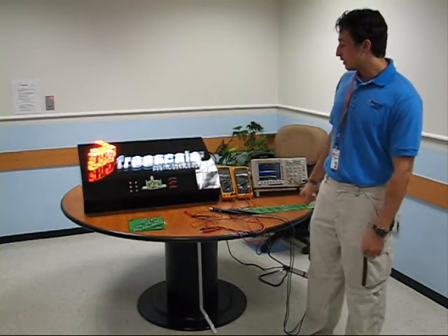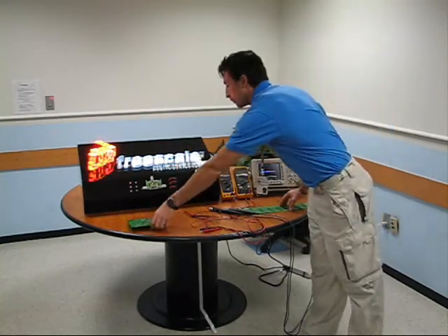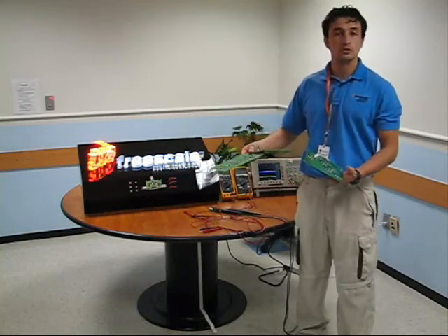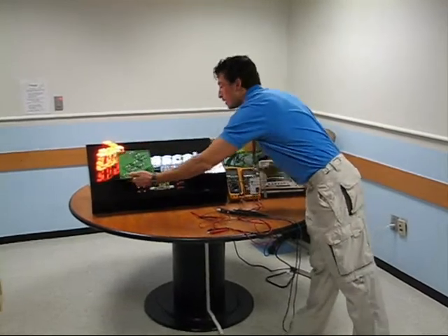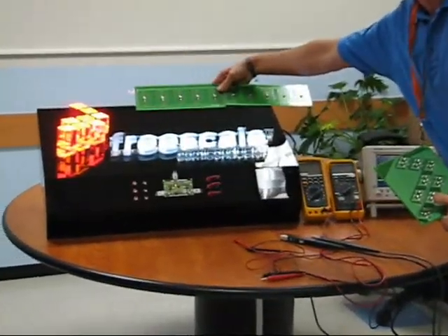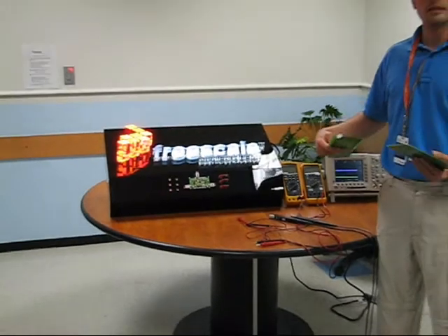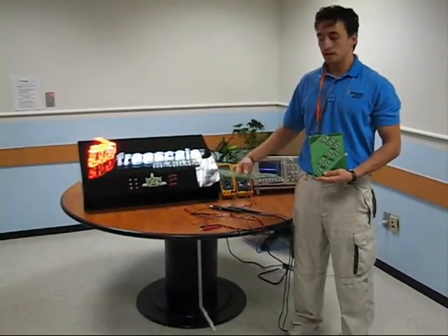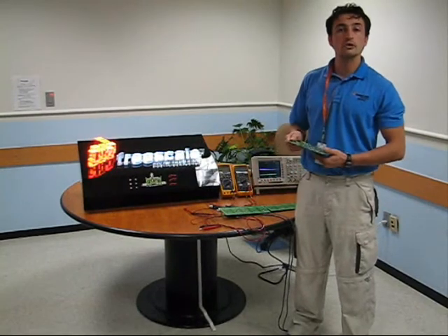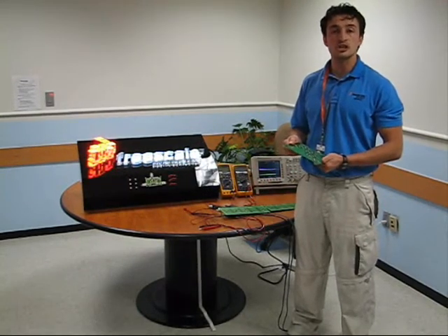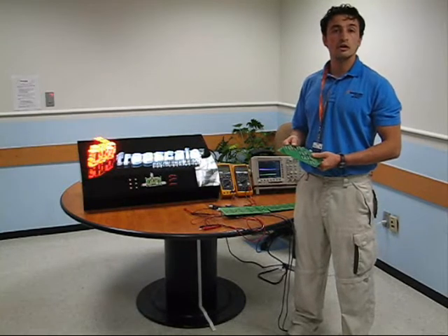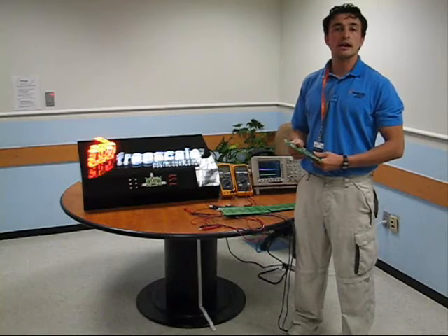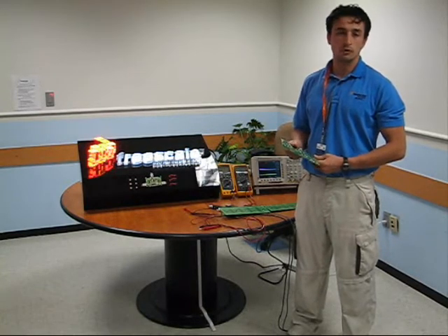So let me tell you right now, we are using our board to supply current to these two internal boards. The first one goes to the logo and the second one in the banner. We are driving high brightness LEDs, 16 of them in the first one and 10 of them in the second one. These LEDs have a forward current of 350 milliamps each, and they are all connected in parallel. So we need a low voltage and a high amount of current to drive the full board.